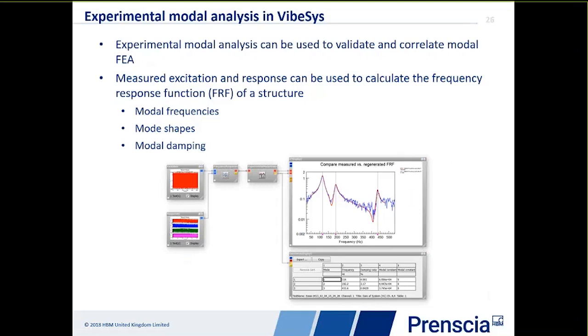Everything that we've seen so far in the demonstration took an FE model where we made static assumptions and then with linear superposition scaled up and down stress states in each of those load cases as they were measured in the time domain. What we would like to do here is try and take into account the dynamic response of a structure. You can imagine things where you might have some sheet metal that is responding dynamically to the loading input.